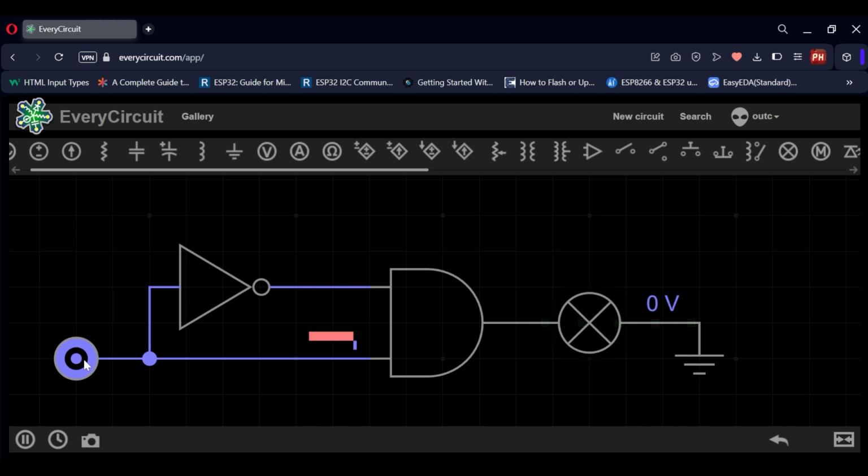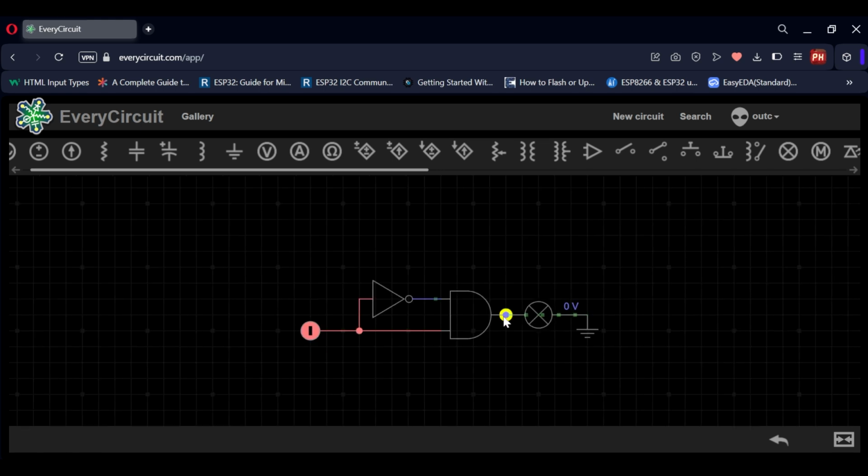So whenever there is a transition from 0 to 1, right now it's 1 here. But if there's a transition from 0 to 1, this becomes 1, but this 1 doesn't turn to 0 instantly. That's why the output stays high and it gradually becomes 0. So when it becomes 0 completely, the output turns off. And in this way, we get a voltage spike at the output when there's a transition from 0 to 1. Let's see the output waveforms.